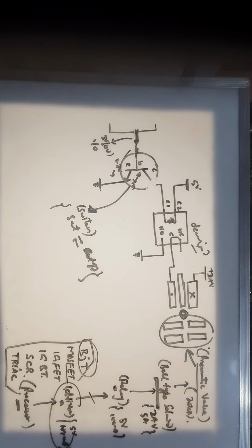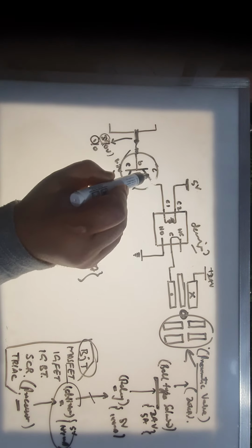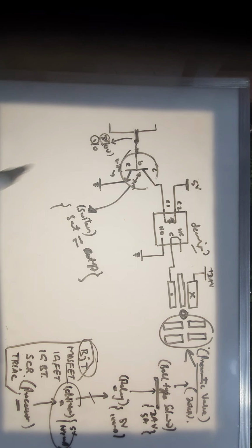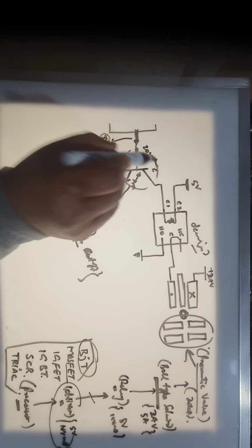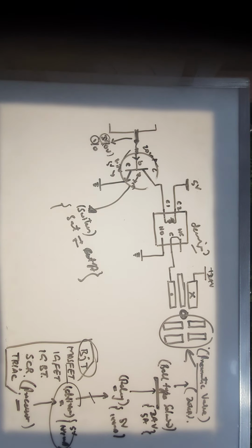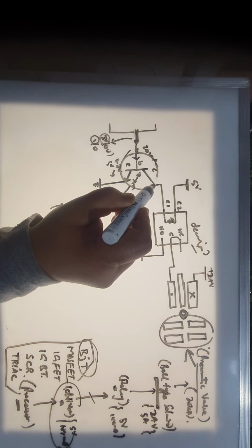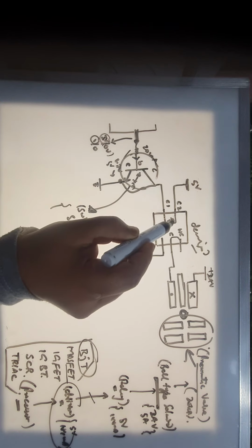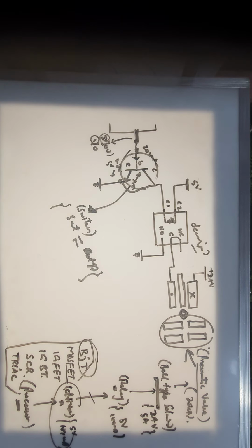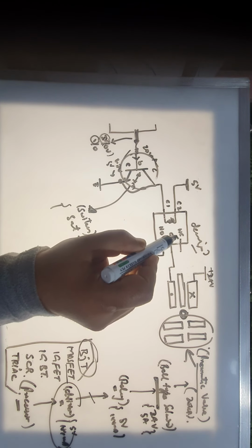Then when you give it 5 volt, that is logic 1, the transistor will operate. The transistor will be given an ample amount of base current, up to 20 milliampere, and it will now have 5 volts, so it will provide the 0.7 volt that it needs to get saturated. When this transistor gets saturated, it is equivalent to C getting connected to E. Now the relay has 5 volts on one side and ground on the other side, so the relay will get operated.